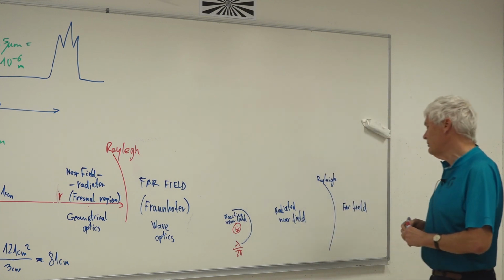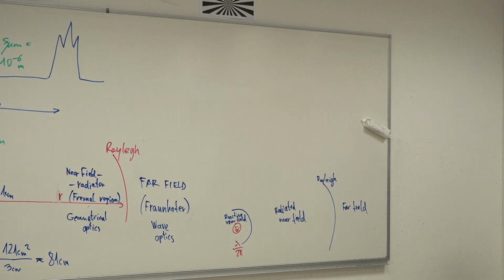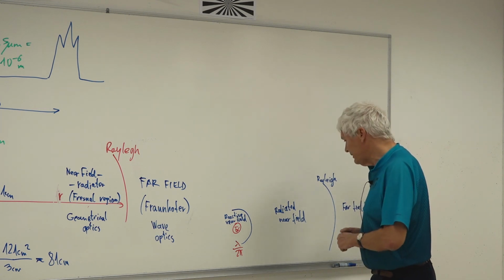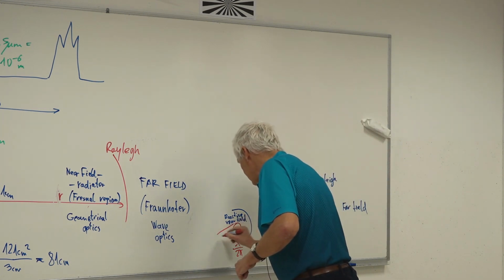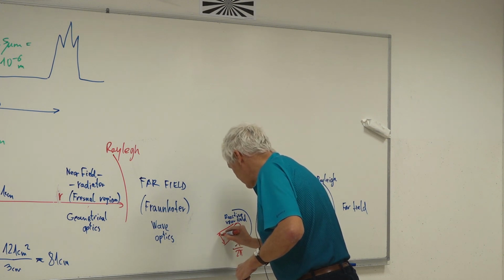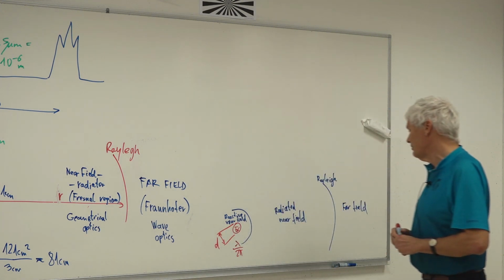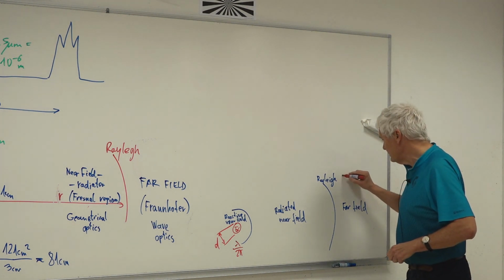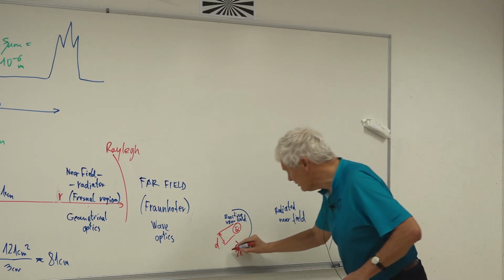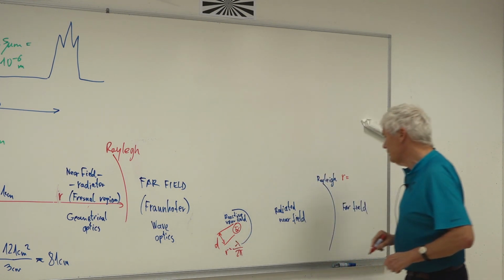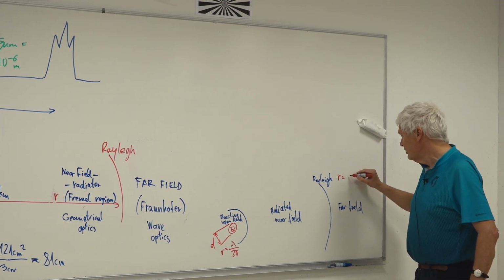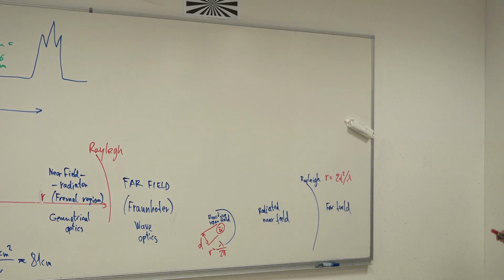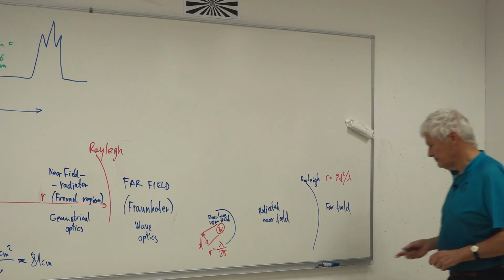So any antenna may have all these 3 fields, though for very small antennas compared to wavelength, this thing vanishes. And this far field is given by the Rayleigh distance, by the dimension D of these antennas. It makes the same if it's transmitting from the receiving antenna, because things are reciprocal. And this is the Rayleigh distance. Here R was lambda over 2 pi from the reactive field, and the large distance is R is now 2D squared over lambda. So that we have all fields defined for the antennas.